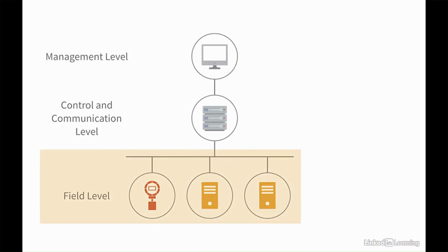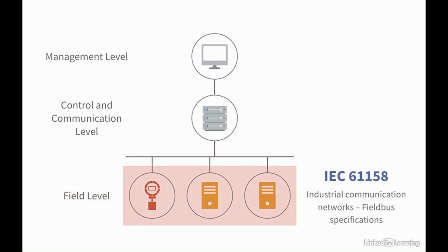For field level, a couple of the network standards for sensors are DeviceNet, HART Communication, and Profibus Protocol. Another example is the IEC 61158 standard, which regulates industrial communication networks fieldbus specifications.